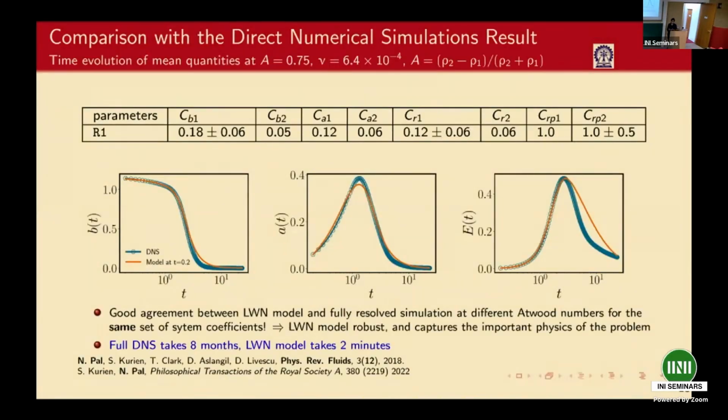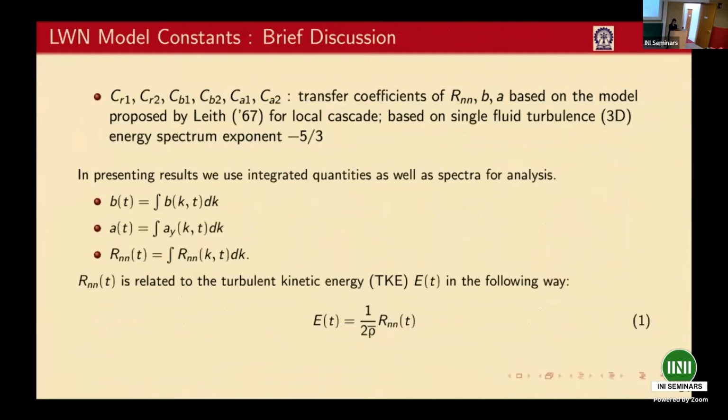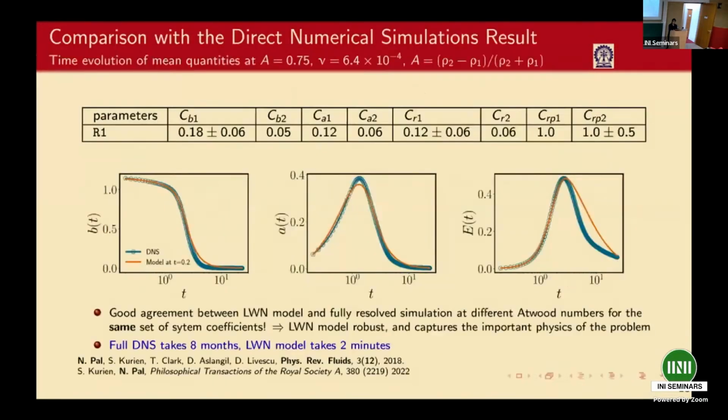After that, what we were studying is, for this two-fluid mixing problem, how does the time series compare with a fully resolved DNS? We saw that the time scales were captured very well in the model. That is the time scales at which the turbulent velocity attained a peak and decayed, and even the energy peak was captured well.